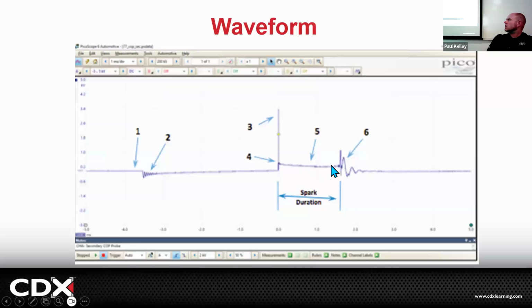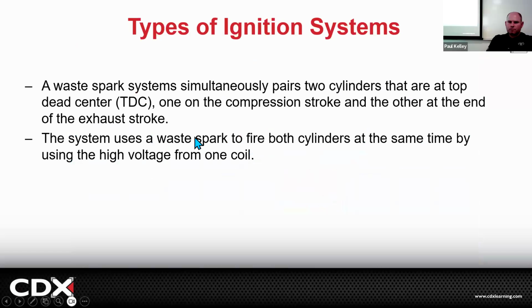And this spark has dissipated the amount of energy that was in the secondary windings, but you might see a little oscillation as it's wiped out, and now you'll see it's a little lower. We switch the coil on, it charges it. We take the ground away, it fires it. Fire line drops. We continue burning. It's depleted. Okay, and round and round and round. Okay, not that bad, right?